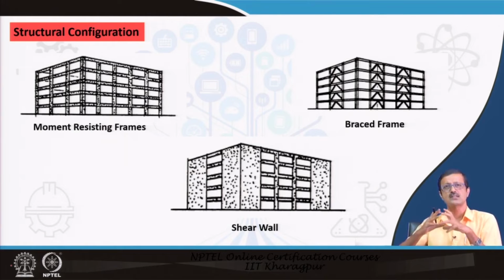So, when these beam-column systems are only beam-column systems, in a monolithic way, or in steel cases as members of beam or column, this is altogether called the moment resisting frame. But this kind of frame sometimes does not serve the purpose. You may have a high degree of loading, maybe wind or earthquake, or because different buildings have differential heights, there is a differential load distribution.